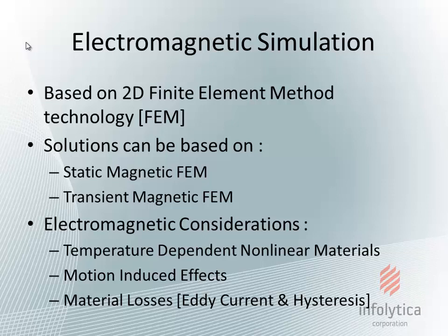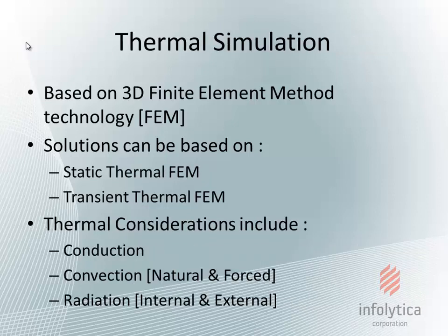In particular, the considerations that we have for electromagnetism include temperature-dependent nonlinear materials, motion-induced effects, and material losses associated with either eddy current or hysteresis effects. The thermal simulation part of MotorSolve is based on 3D finite element method technology.